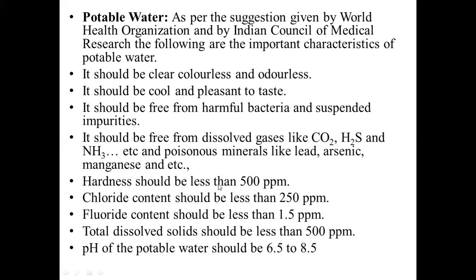Hardness is important. Hardness should be less than 500 ppm, not greater than 500 ppm. If it is greater than 500 ppm, then the taste of water will not be proper for drinking purposes. Chloride content should be less than 250 ppm. Fluoride content should be less than 1.5 ppm. Total dissolved salt should be less than 500 ppm. pH of potable water should be around 6.5 to 8.5. These are the characteristics of potable water. Very important.